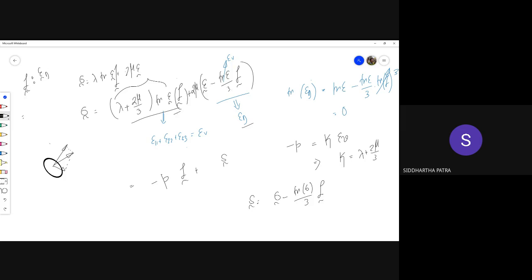But now you know that in the identity tensor, the only three terms that are non-zero are the diagonal terms. So basically this would mean epsilon d 1 1 plus epsilon d 2 2 plus epsilon d 3 3. And you know that this would be the trace of epsilon d, and the trace of epsilon d happens to be 0. Since this matrix inner product is 0, they are mutually orthogonal matrices. My point being that this representation is unique.